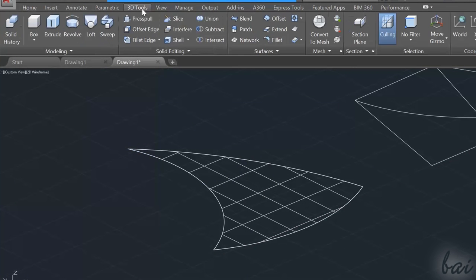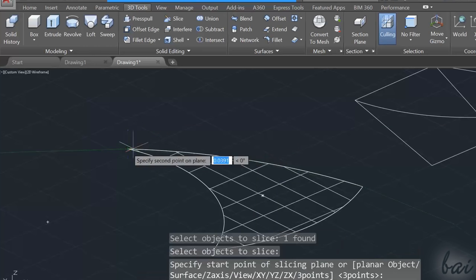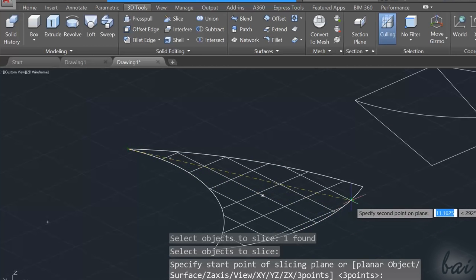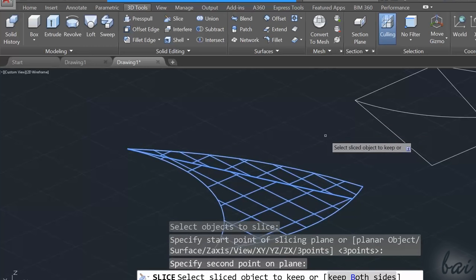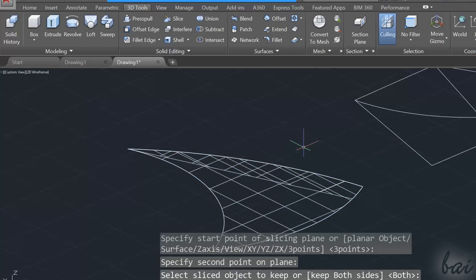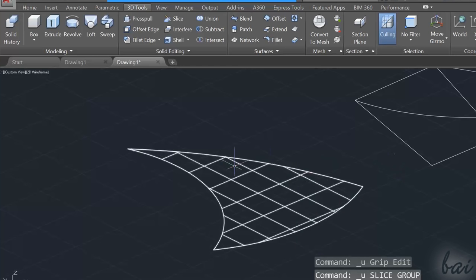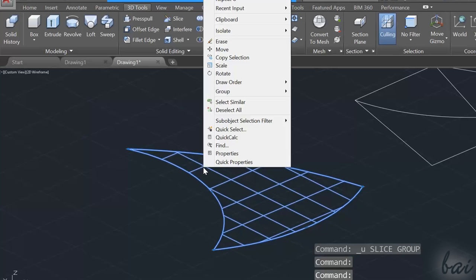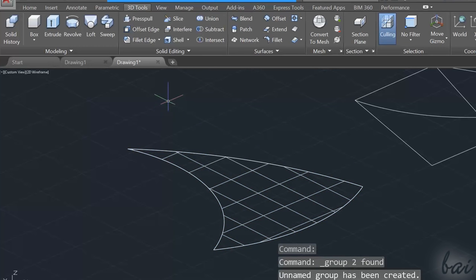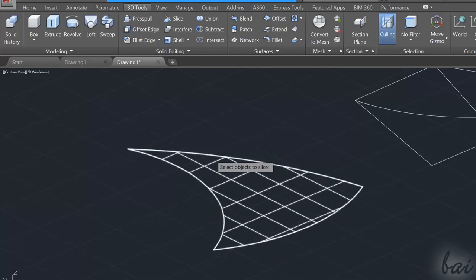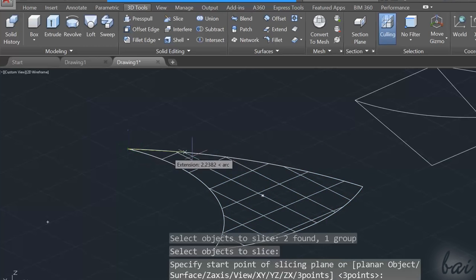These surfaces do have an area, but not a volume, but are treated just like 3D objects like solids filled and checked inside. Being 3D objects, the 3D editing tools do work on the surfaces, but not their 2D boundaries. So, if you select both the surface and its boundary, right-click and go to Group. You will group both the surface and the boundary. In this way, all the tools you are going to apply will be effective.